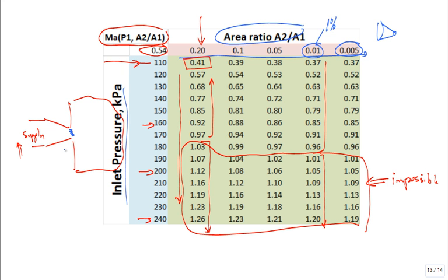Somebody says, well, make it neck down even more. Well, you're still just having a smaller area that's choked, or Mach 1 right there. Okay? So this whole range is I cannot have simply a converging nozzle, only the cross-sectional area is converging, and expect to get flow out the outlet that is supersonic. Something's missing. Okay. So now I have to jump and get to another file.